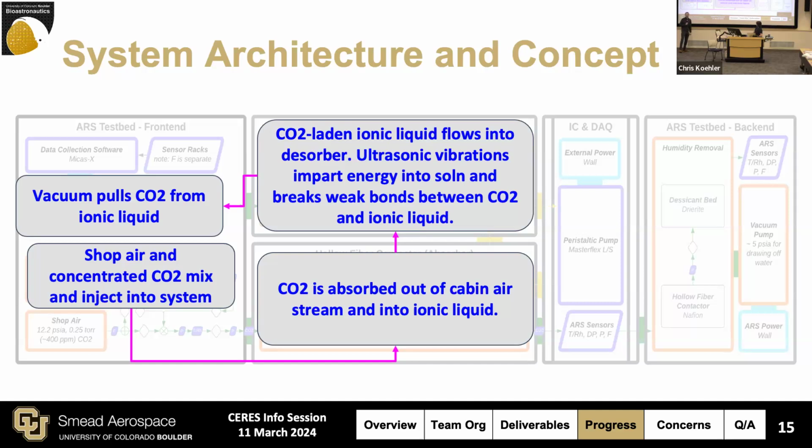We're trying to use ultrasonic energy to vibrate it out effectively. What that means is the ultrasonic vibration is at 40 kilohertz, and the really, really fast vibrations are at very low amplitude. And so it creates very small vacuum bubbles within the liquid called cavities. This cavitation effect effectively creates really low pressure areas that the carbon dioxide can come out into, where it prefers to be rather than dissolved in the fluid. And then those bubbles will just be released by the fluid.